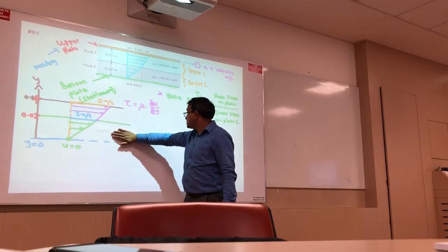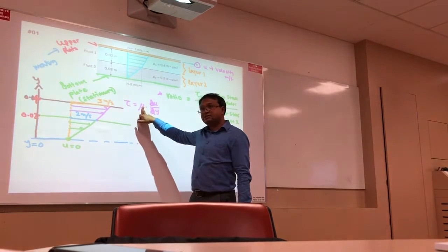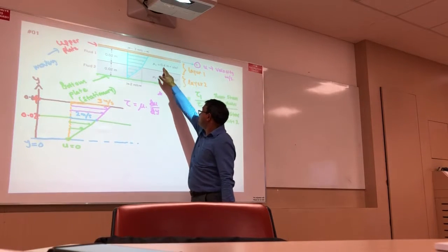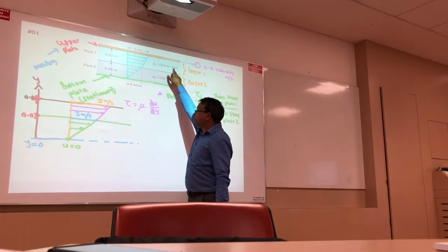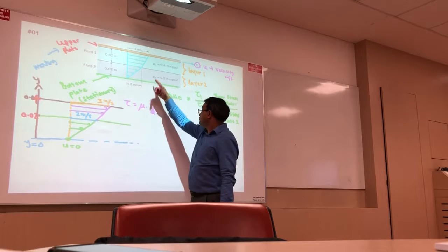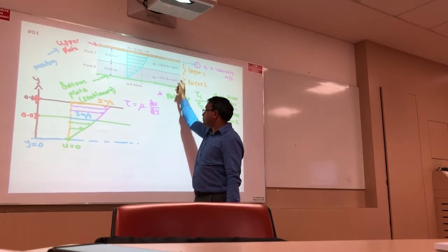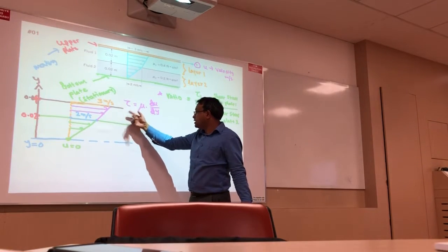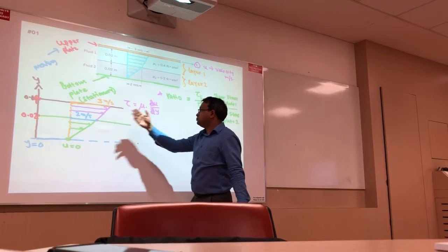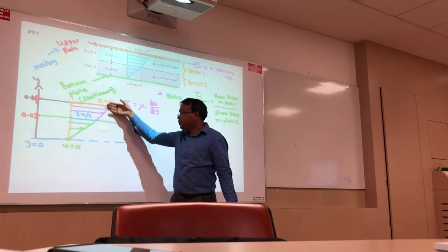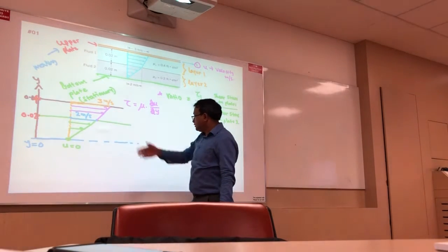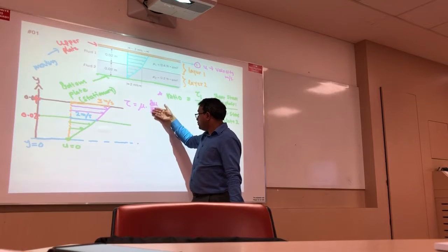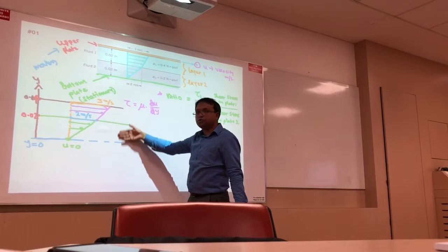So what is the shear stress equation? Mu is the viscosity. So at the point the viscosity is given 0.4 Newton second per meter square. Layer 2, the viscosity is 0.2 Newton second per meter square. It's very simple. Tau 1 is mu 1 du by dy in layer 1, right? And layer 2, tau 2 is mu 2 times du by dy at layer number 2.